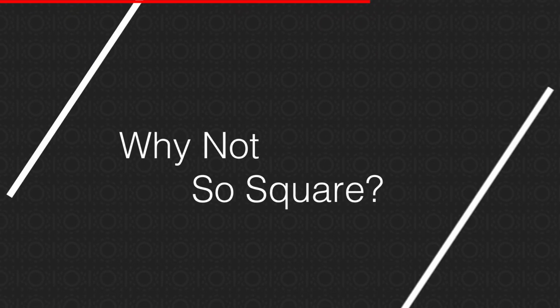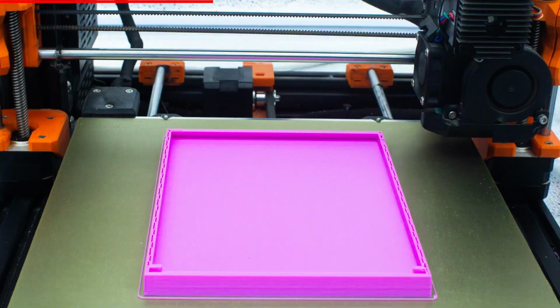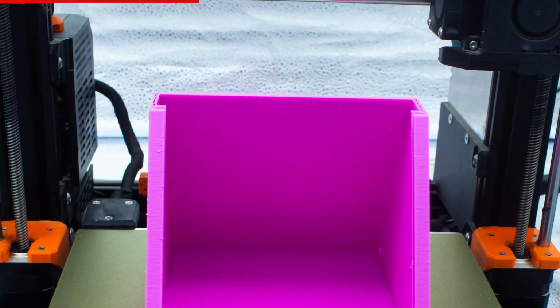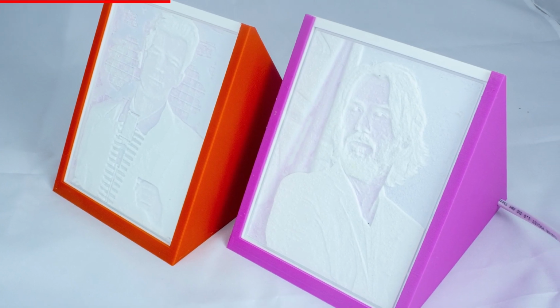As for some of the design considerations, one of the easiest and most natural shapes a person thinks of is a cuboid. But the reason for this lamp being prism shaped and not a cuboid is twofold. The first one being that I find triangular designs more aesthetic, and the second being that cubical designs would be much harder to 3D print. There are slots on the sides where the lithophane would be inserted. If it were a box, it would be very difficult to print this without supports. A triangle, however, is easy to print without any supports and also allows a nice slant to make it easier to look at, much like a photo frame.